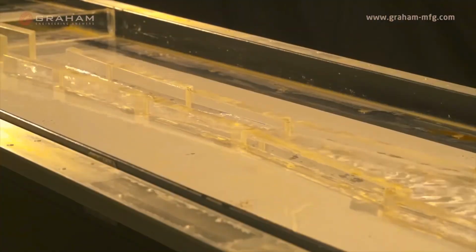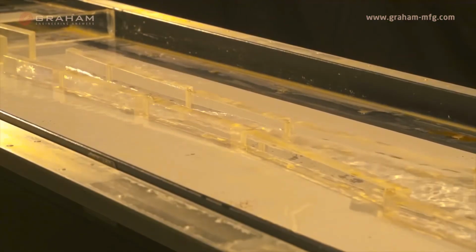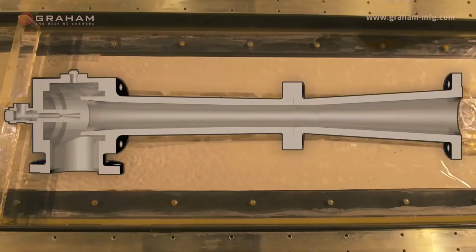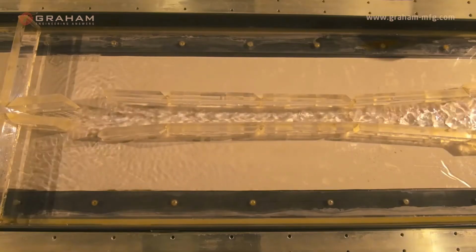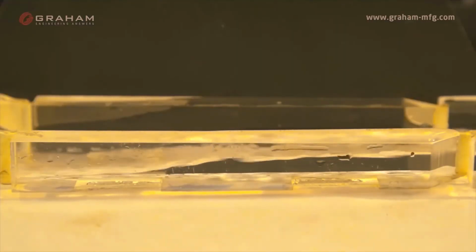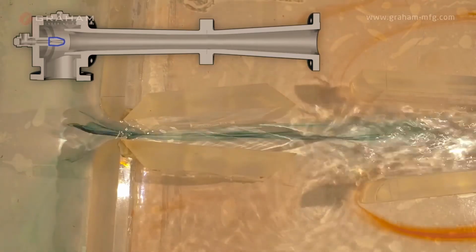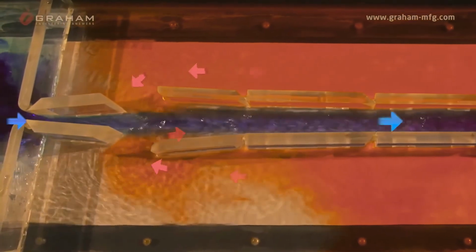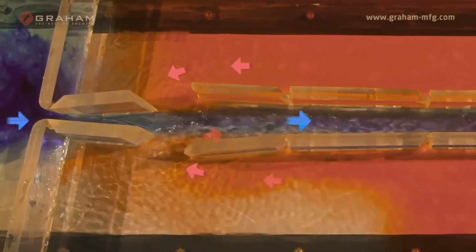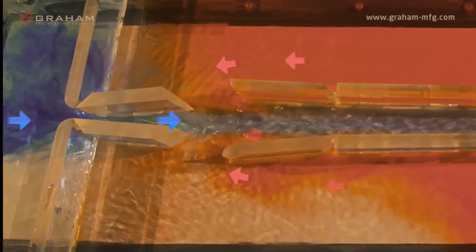To further expand on the principles of operation, here we have a two-dimensional hydraulic simulation of the flow through an ejector, which can be visualized on what we refer to as a wavetable. The height of the water in the wavetable is analogous to the pressure in an ejector. The motive nozzle expands the high-pressure motive fluid down to a pressure lower than the designed suction pressure. As the high-velocity motive flow leaves the nozzle, it comes in contact with the suction fluid and begins to mix with it, entraining it as you can see here. The pressure will slightly increase through this section, causing the water level on the wavetable to rise.